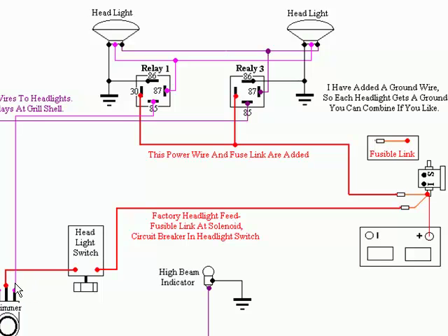And the dimmer here basically tells the relay to do this here, or the other one, the high beam, tells the other relay to do this here and connect and make it a high beam. But notice that if something here is broken on one of the headlights, then the other one is still functioning because the current can run through the headlight.